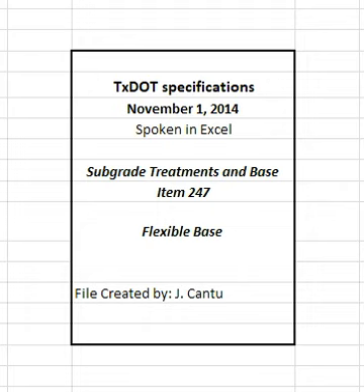2.1.1 Material tolerances. The engineer may accept material if no more than one of the 5 most recent gradation tests has an individual sieve outside the specified limits of the gradation. When target grading is required by the plans, no single failing test may exceed the master grading by more than 5 percentage points on sieves number 4 and larger or 3 percentage points on sieves smaller than number 4.